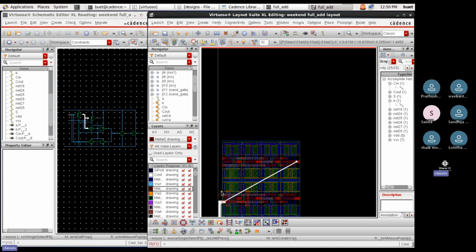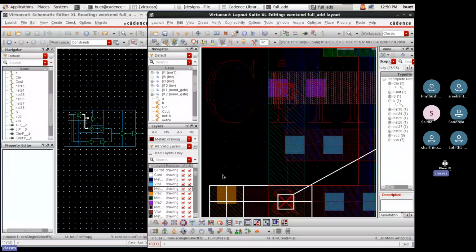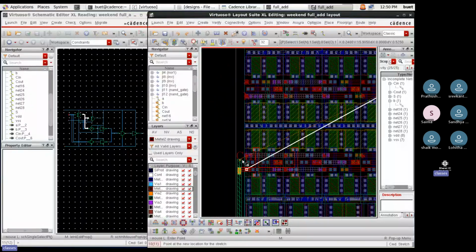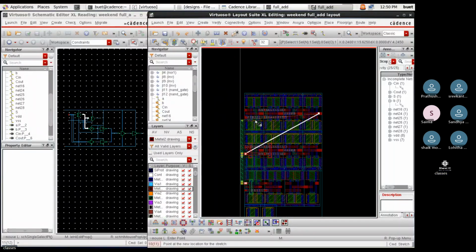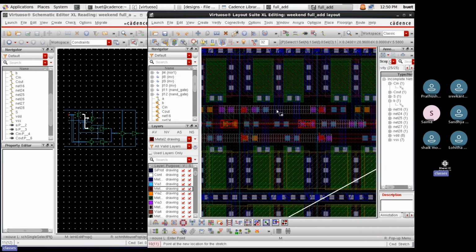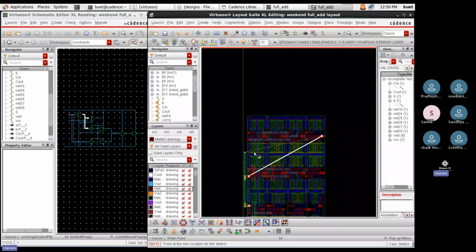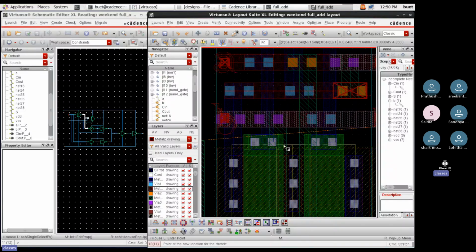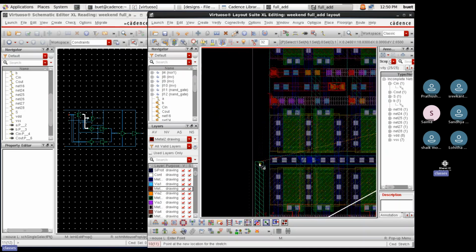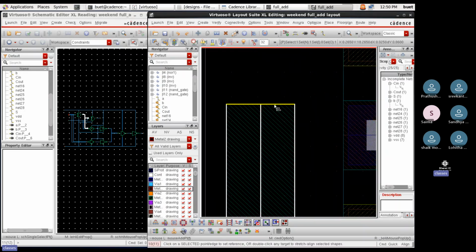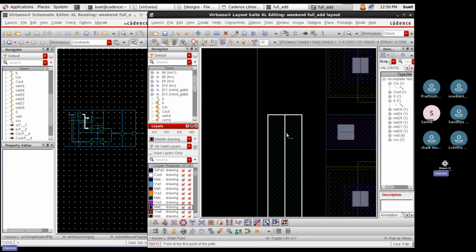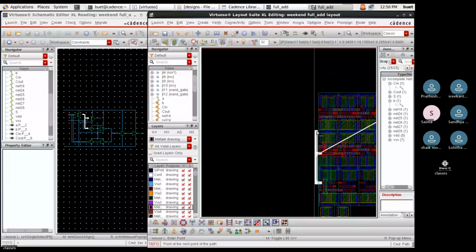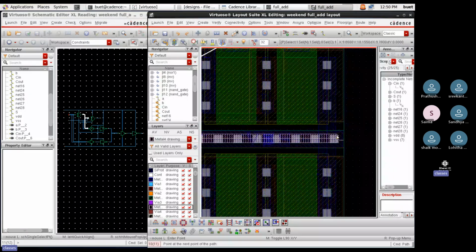Then what I can do here is I can simply go here. I can pull this metal again from here, and I can come up till this level. Okay, M4 is already there. I cannot draw an M4 again at this level. If you see, all three tracks are filled with M4. The only way to pull the M4 here is either on the device or on this track line. Here I can draw an M4, simply I can draw an M4 here.